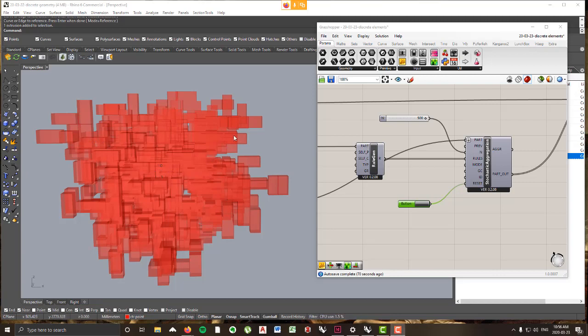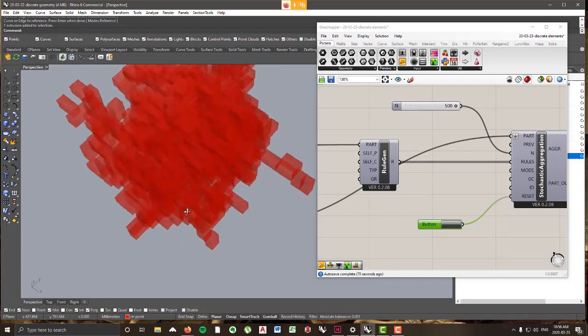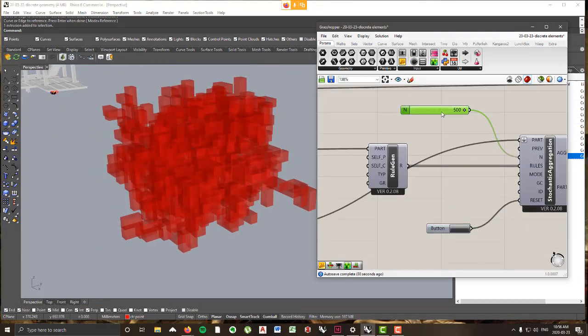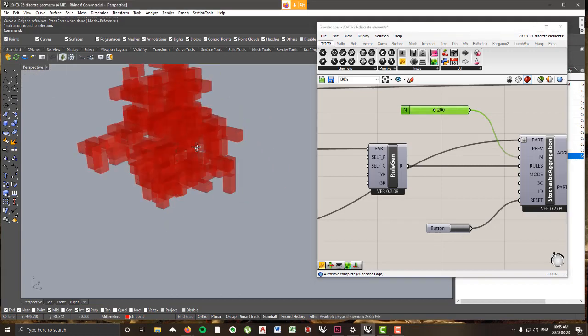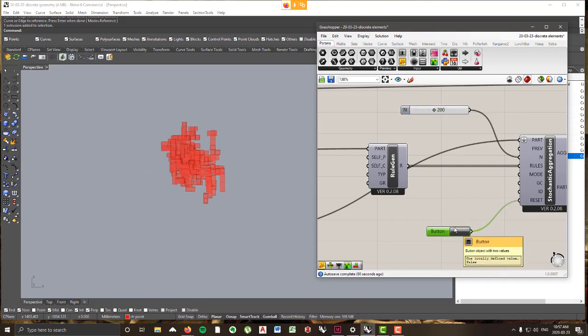The reason why that's happening is because we haven't defined any specific rules. Essentially, we've just told WASP to array any way you want, do whatever you can, and you see when I hit reset, it's just giving us these random agglomerations of parts, which looks kind of cool, but maybe we want a bit more control over it. So this is how we can edit WASP syntax to define what connections can and cannot be made.